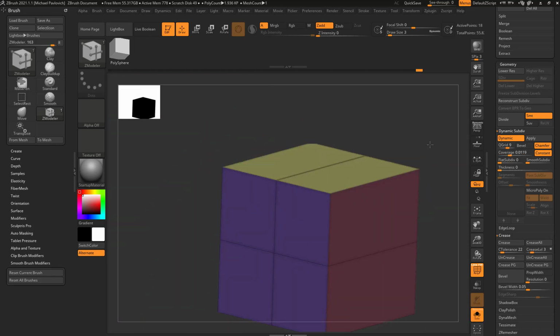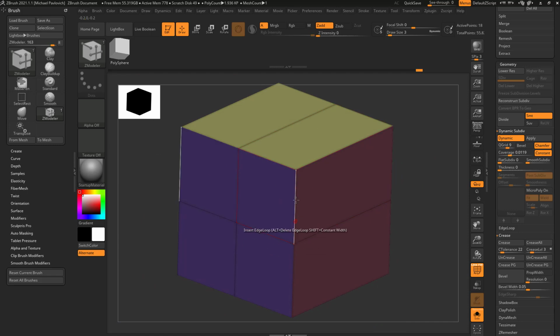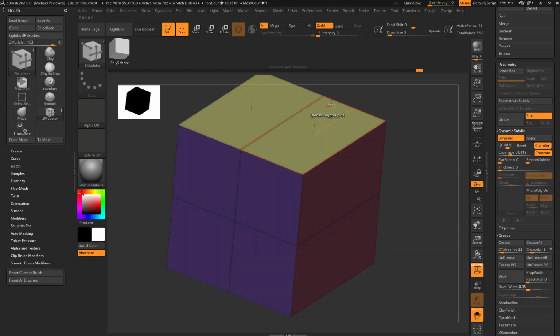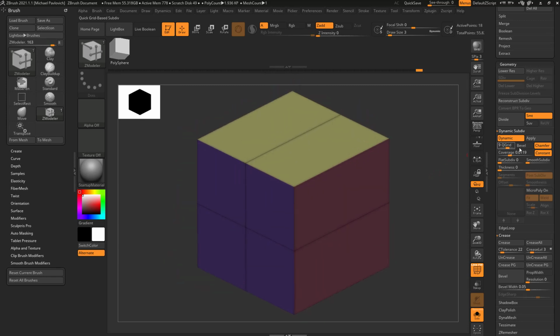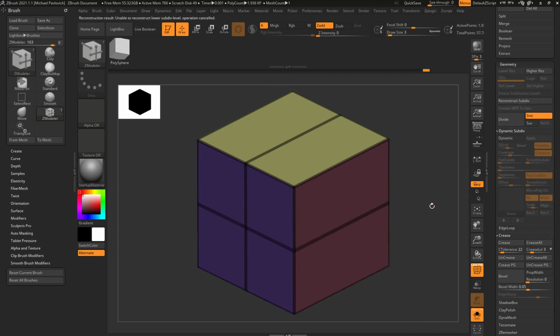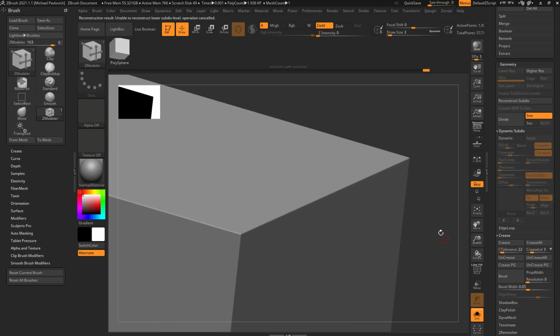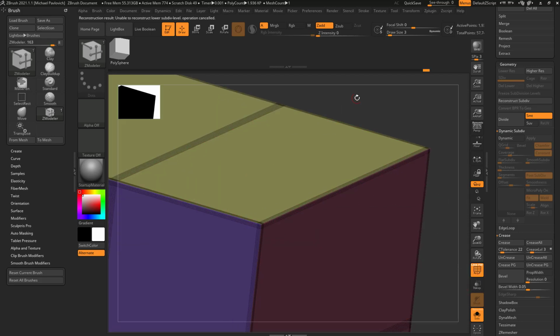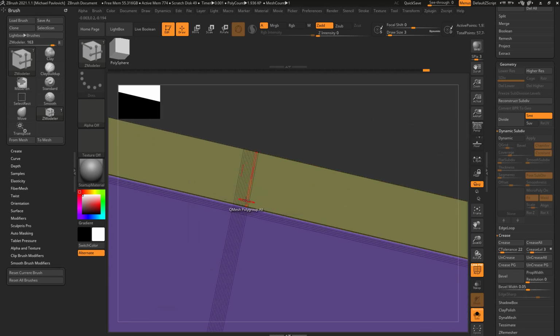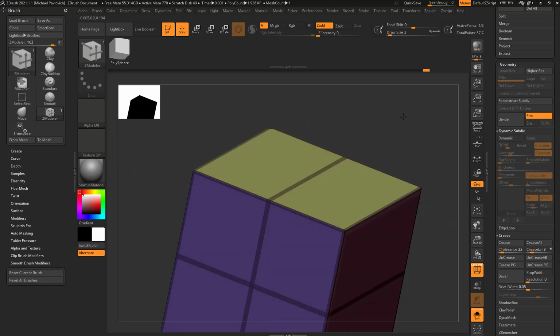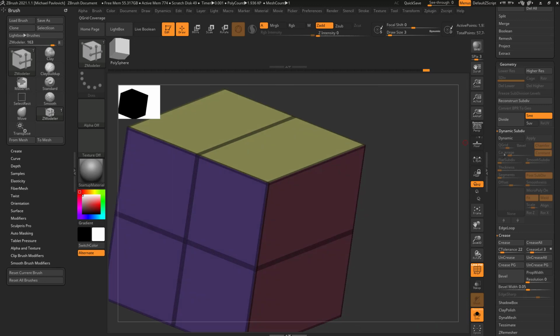And normally when it's very blocky meshes, it's just every visible edge you see. However, just keep in mind it is packing edges in internal edges that you have as well. So if I take this and we don't have smooth and we hit apply, you're going to see I don't have geometry here. And if I hit reconstruct, it's not going to be able to. All it's doing is packing edges on every single edge based on my QGrid resolution, and my coverage is telling it these edges are packed closer or they're packed farther apart. So that's the difference between QGrid and smooth subdiv.